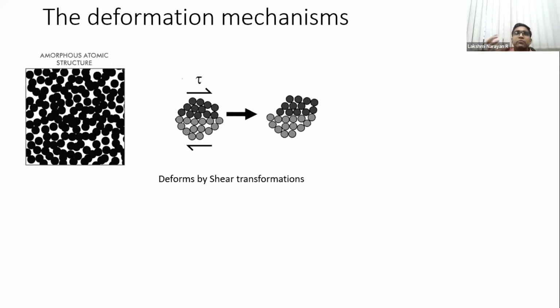So whenever you see deformation mechanisms in metallic glasses, it involves dilatation, or expansion of the volume. This kind of deformation has to be associated with extra volume, which is why free volume is an added picture. If you have a very crowded space, it's much more difficult for the cluster to move. If you have more free volume, the cluster finds it easier to undergo shear transformation.